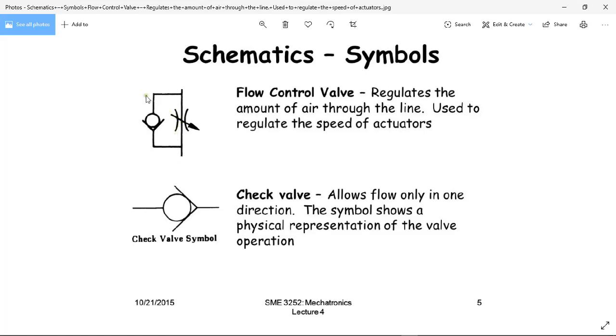But in the other direction, it is not regulated. For instance, if you're applying pressure from bottom going up, the pressure that you apply here is the pressure you're going to get here, because it is unregulated. It goes through the throttle, it finds resistance, it comes this side, it's an open way because it will push the ball and the ball will open, then it will pass through.